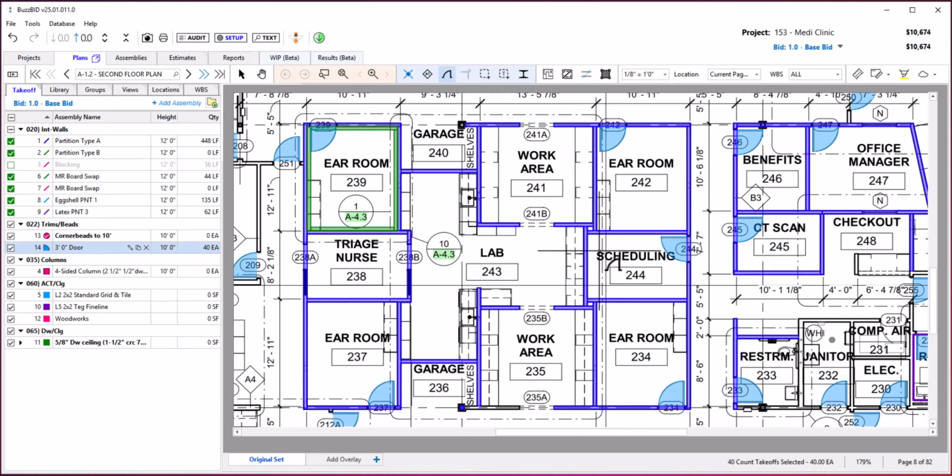We always ask you to give a visual sweep of the plans and see if you agree with everything, because sometimes the plans, the PDFs, are too convoluted and it might fool the computer vision. In this case, the door right down here got left out, so you have to add that one manually. So always check your plans.